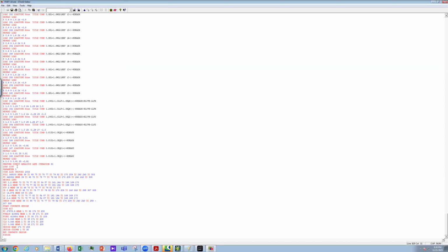So load list 101 to 168. So the software will design following only these load combinations. You may have more combinations, but you can define for which combinations the software will design your members. We can have more combinations, no problem, but we will not include them in our design. So keep this in mind.